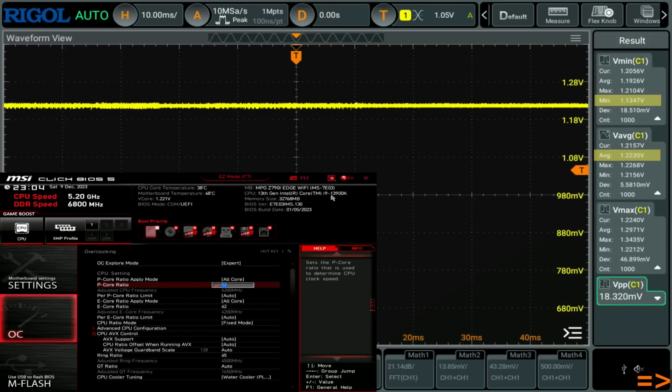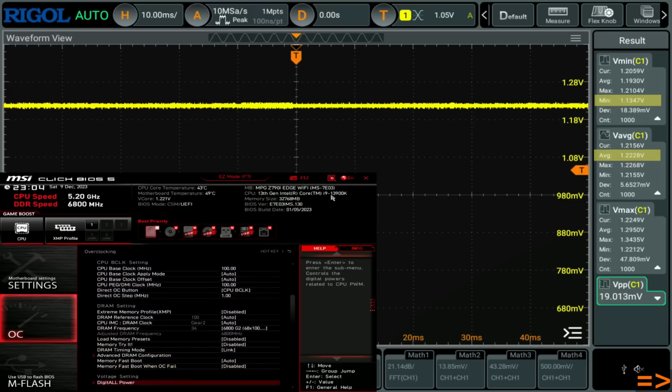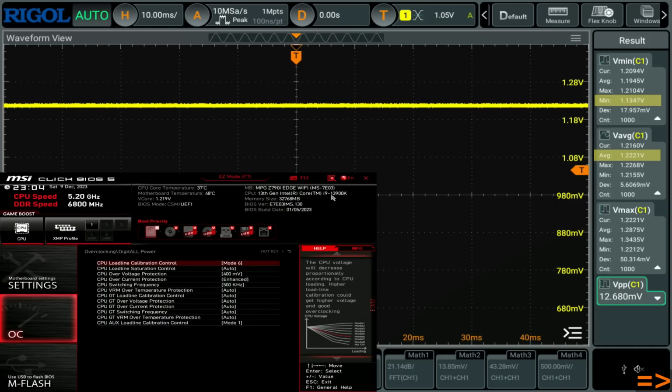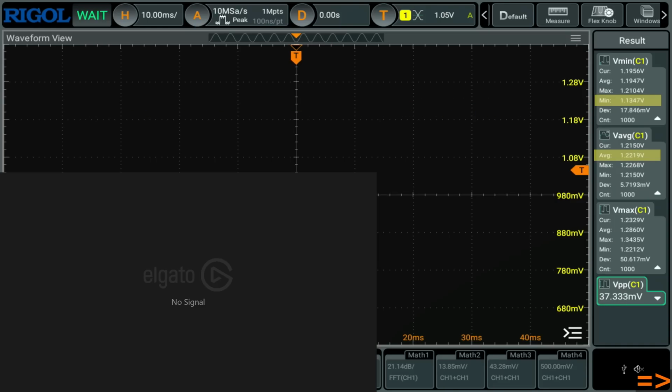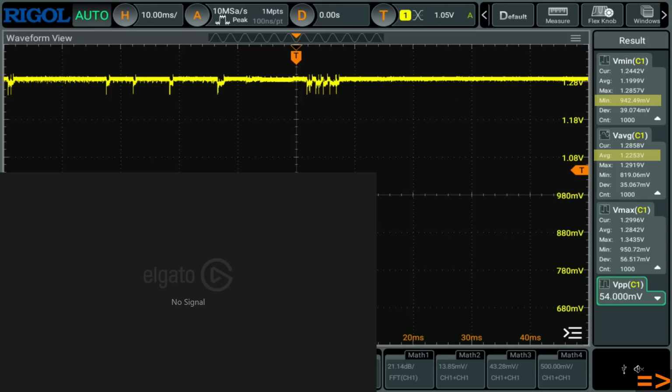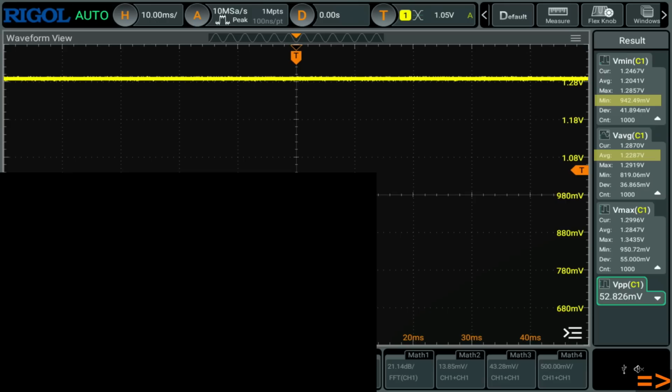Anyway, now we're going to go to mode 6, which is actually going to start cleaning things up a bit. So we're going to go to 1.3 volts and mode 6. I guess we could also try 1,000 kilohertz switching frequency at mode 7 or something. Actually, no, I don't want to try 1,000 kilohertz. The thing is, I've seen motherboards where the maximum switching frequencies are various levels of broken, which is not good.